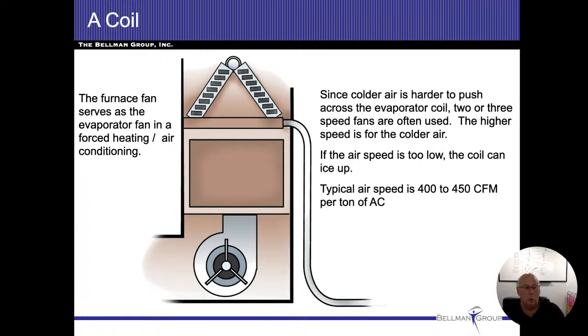All right. So when you're going around and you got the air conditioning running, try to hit every single room and make sure you got a decent airflow coming out of there. Some people, and Mark, if you're still here, I know you're going to know this answer, use a wind or an airflow monitoring device, and I'm drawing a blank on what that's called right now, but they put that over the ductwork, and I kind of like that idea because now we have a definitive number. And then if we have one room that's significantly less than the rest of them, that could actually be an area where we're going to have trouble heating or cooling.